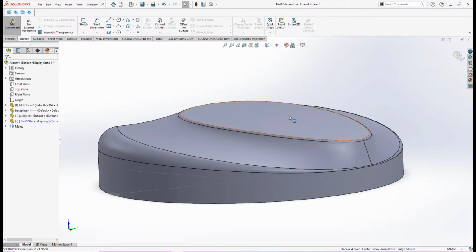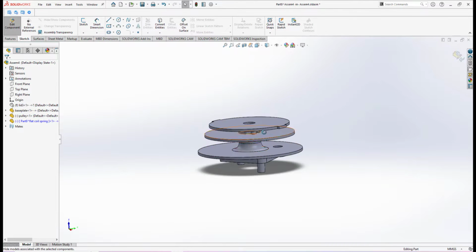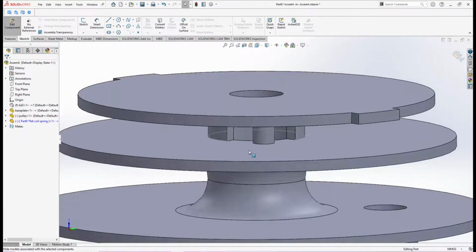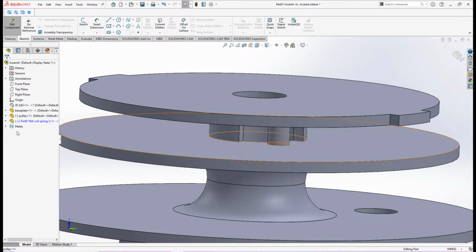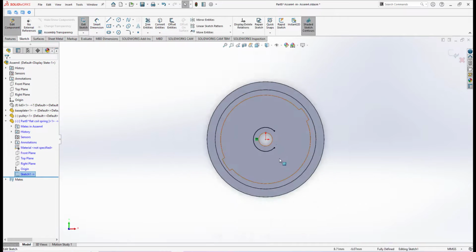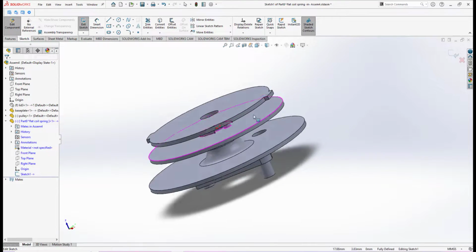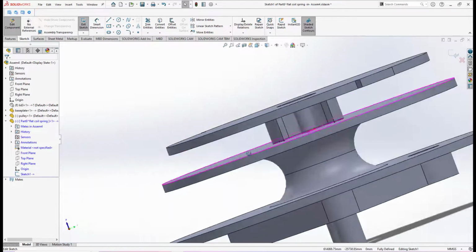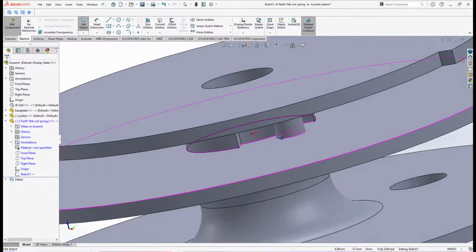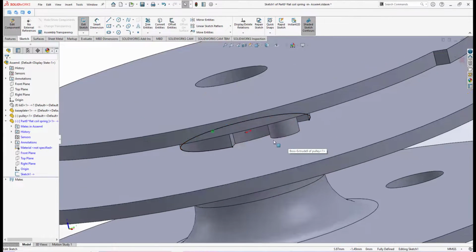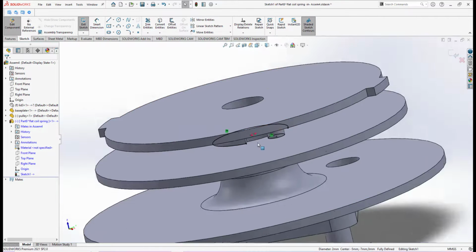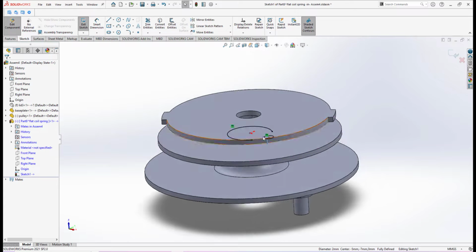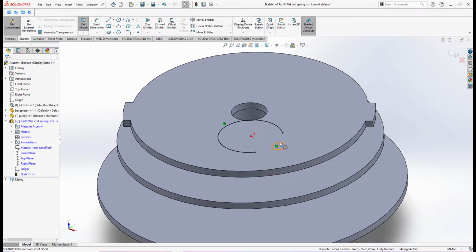Let me turn off the section view and let me hide this lid for a while. And also, if you look, I have a trace image, that curve I have just converted to entity. So under this part 8 again, under this sketch mode, I click edit again. I need to trace this spin also, because this trace curve is my guide curve for me to do modeling of this coil spring. So these circular edges also need to be converted to entities. So I have this trace curve.